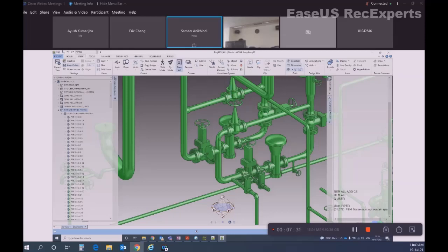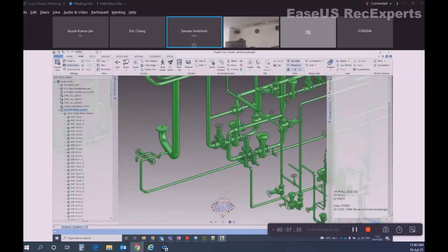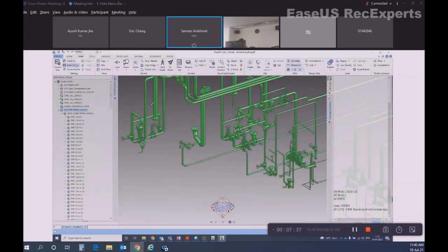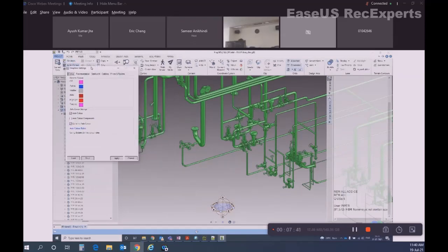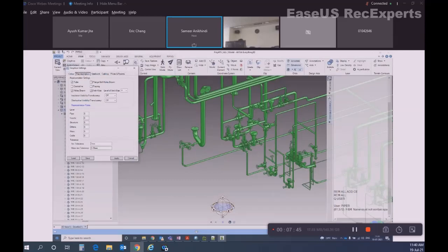So how to turn on that obstruction volume and insulation volume? You have to go to View, Graphics, in the Representation tab. You have a couple of things over here, out of which insulation visibility and obstruction visibility. Here for insulation, you can choose solid insulation or some translucency.